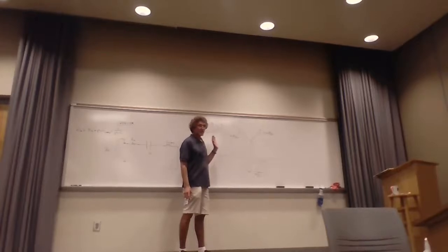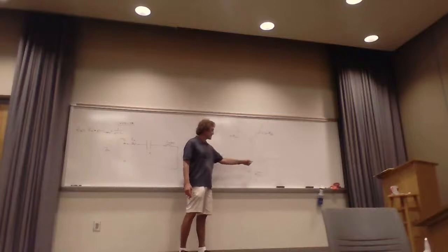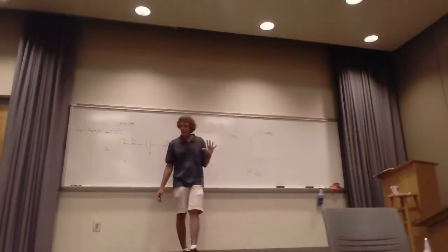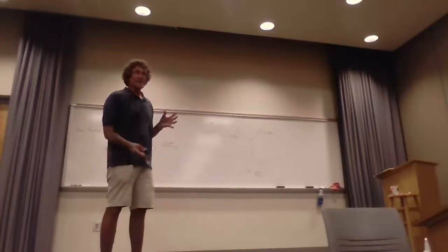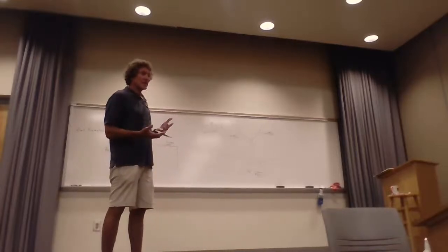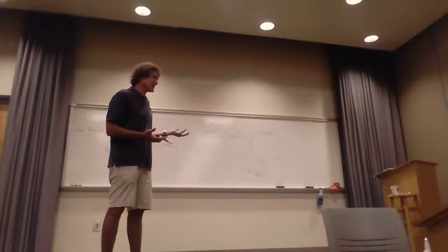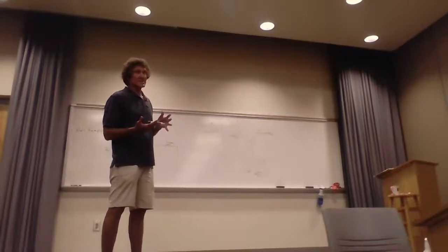If you're setting up an LC circuit to resonate at a certain frequency, say 100 megahertz, you want the self-resonance of both the inductor and the capacitor to be at least an order of magnitude away from the resonance you're targeting, or else you're going to have problems. Because now the capacitor's inductance or the inductor's capacitance will start to affect the resonant frequency.